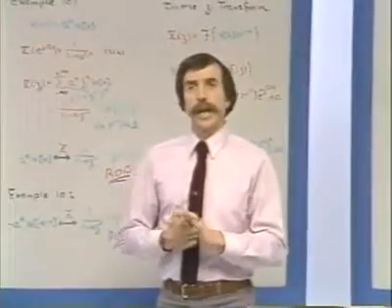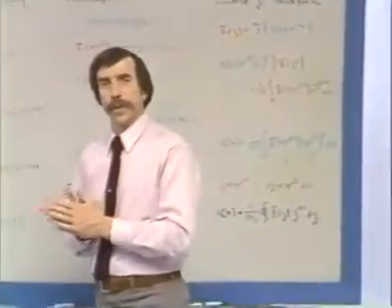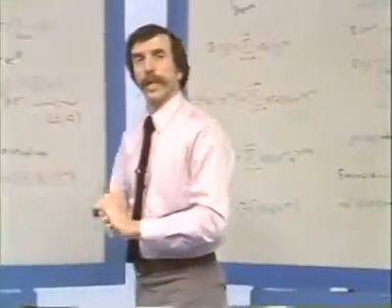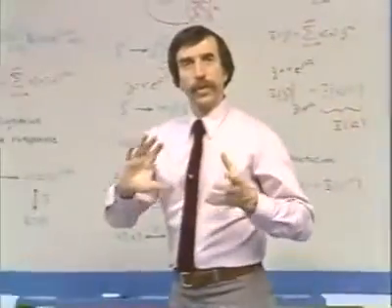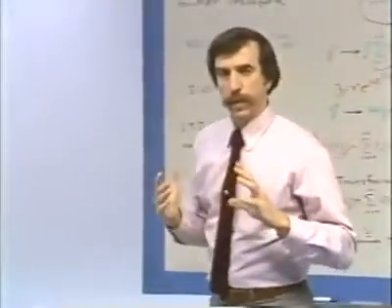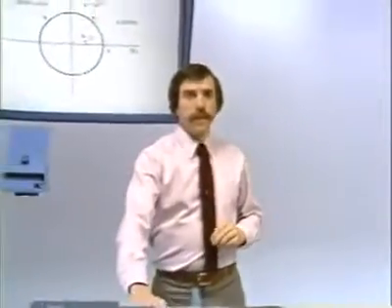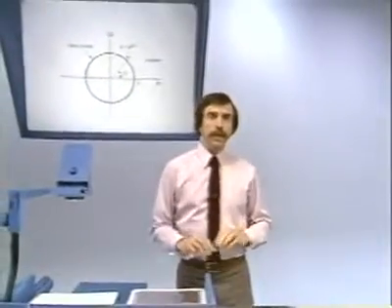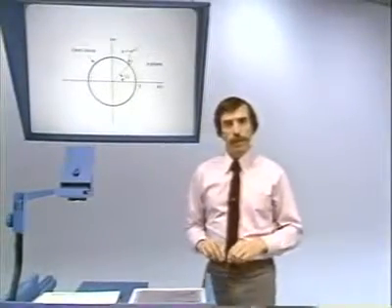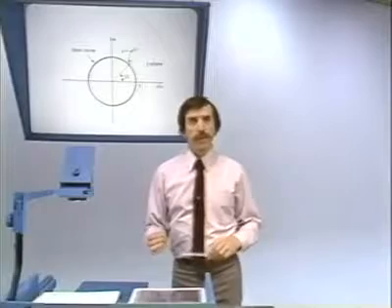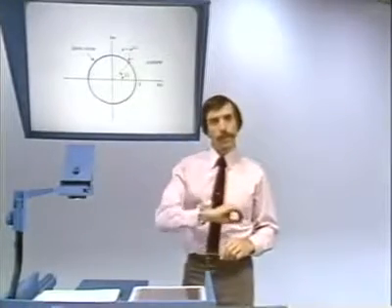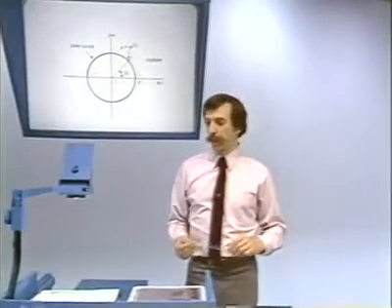And also, as with the Laplace transform, it's convenient in looking at the z transform to represent it in the complex plane. In this case, the complex plane is referred to as the z-plane, whereas in continuous time, when we talked about the Laplace transform, it was the s-plane.